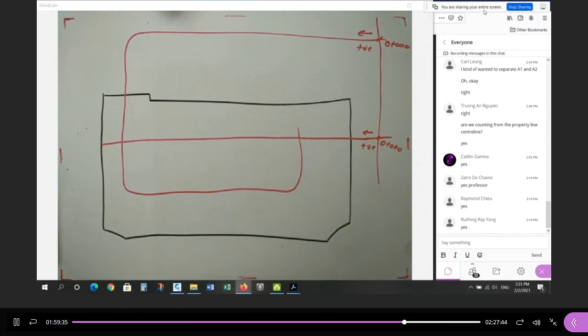The design for the overland flow, remember the purpose of the profile is to promote flow overland along the road. So imagine the storm sewers get full of water during one of the big events, right? The storm sewer is designed for, I think, the 10-year storm. So anything statistically bigger than the 10-year frequency of storm, the pipes will be full, and then the roads act like rivers, right?